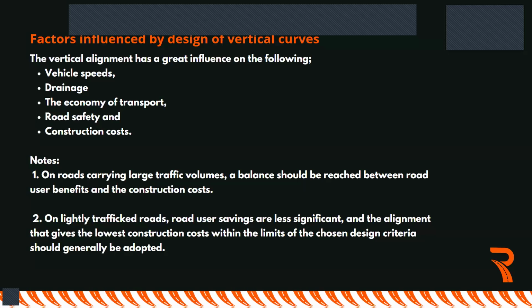You notice that the long distance transporters tend to avoid it because the curves are a little bit too steep, and they find high consumption of fuel, of course, because the section is a bit hilly, and therefore the design engineers used quite a steep slope. And then there is the aspect of road safety: stopping sight distances, passing sight distances, and headlight glare.